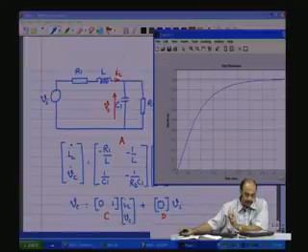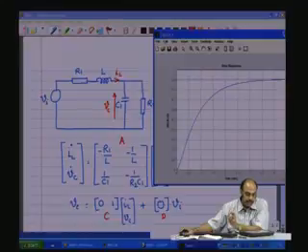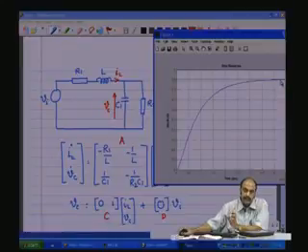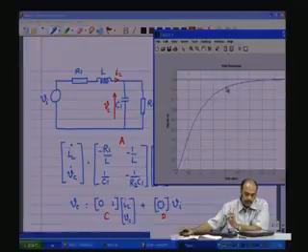Then as time progresses, the capacitor gets charged through the current here and the voltage starts building up, and in the steady state, that is in the DC condition, capacitor is open once it is fully charged, and during that time R1 and R2 share, because this is 1 ohm and this is 10 ohm. So, 10% goes to R1 and the remaining 90% goes to R2. So, this is how one, and the rise time is as given here.